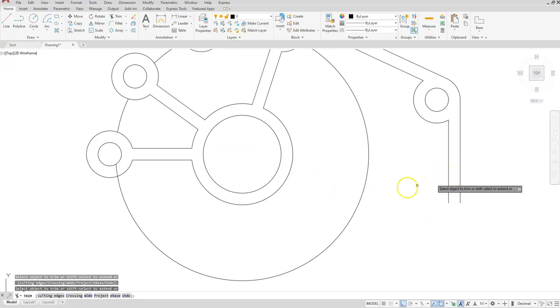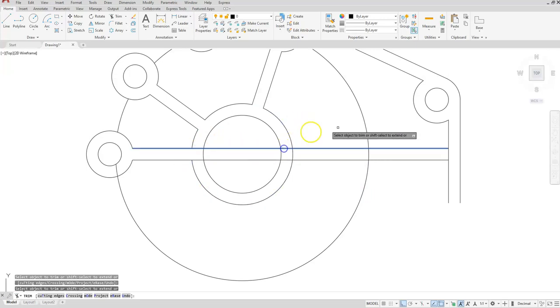So I'll hold down the shift button and keep it held down, and then I'm going to keep clicking on this line at the end points. So you can see that I'm kind of walking it back to where I want it to go. I'll do the same with this one, so I'll click here. I'm just walking this line back. And also make sure that you keep that shift button held down throughout the whole process. Release the shift key.